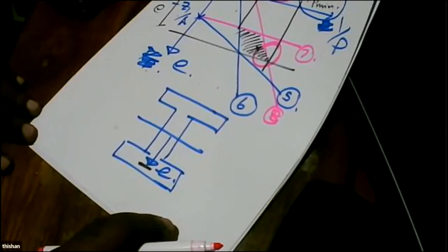Because of that, it gives a strength of 1860, whereas reinforcement is manufactured with some modifications, and we generally limit it to 500. So this is about 3.5 times stronger than reinforcement, and we have to pay a cost penalty.